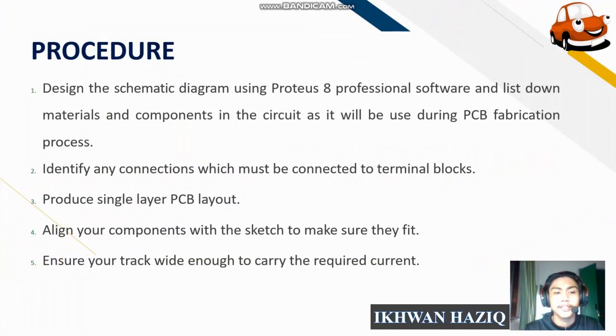First, we design the schematic diagram using the Proteus 8 software and list down the materials and components in the circuit, as it will be used during the PCB fabrication process. Second, we identify any connection which must be connected to the terminal blocks and produce a single layer PCB layout.